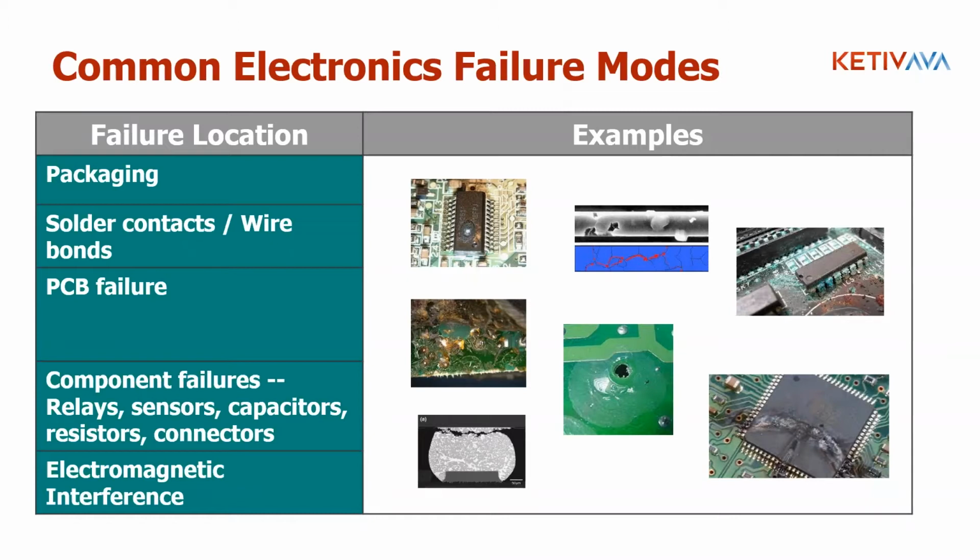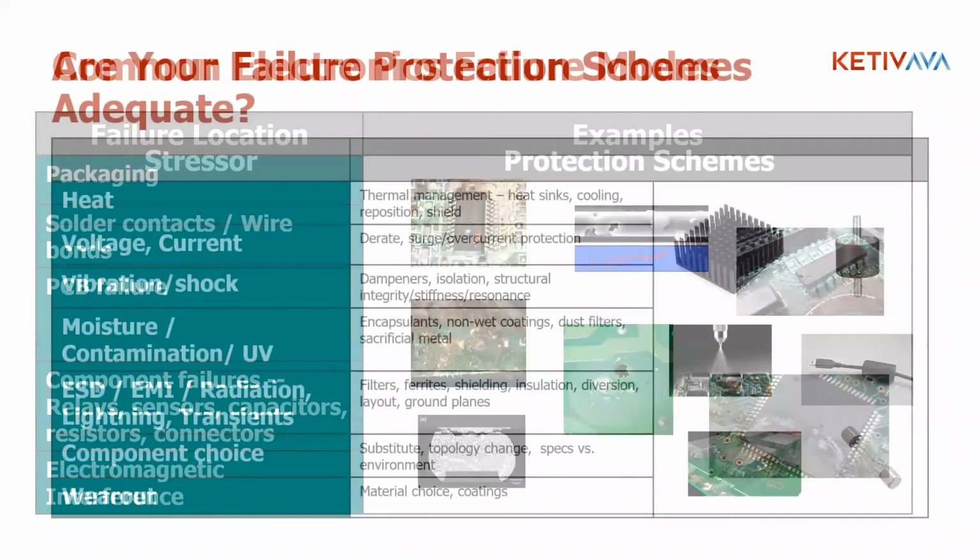And these stressors that cause failures include high temperatures, electrical and mechanical shocks or stress during use, high humidity, contaminants, electrostatic discharge or material aging, or external EM fields, all as presented here on this slide. And electronics reliability is to try and mitigate these failure modes.